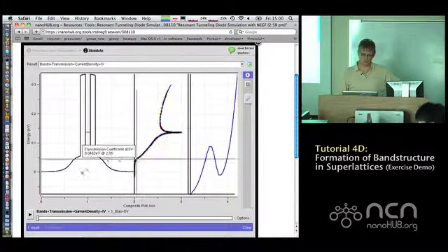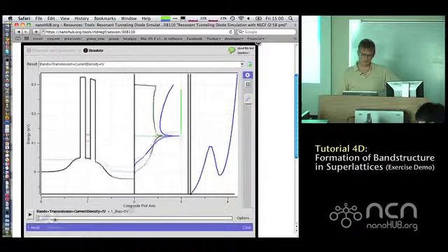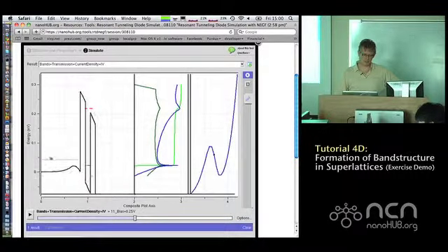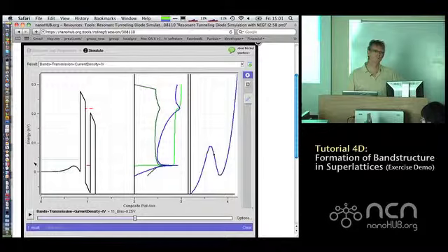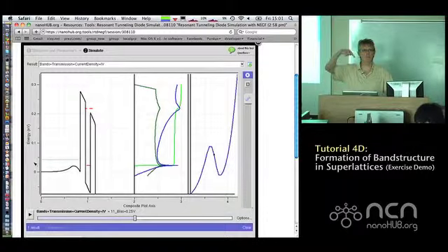Going back to this one question here. So look at this, here is a heavily doped semiconductor. It's degenerately doped. The Fermi level is at 41 millielectron volts above the conduction band. This is like a quasi-metal, right? There's tons and tons of states, and they're all occupied with electrons, right? So that's what we call contact. But further out on the left, there will still be the metal contact. Okay? So I'm not quite sure what you mean by air. I mean, if you think of an STM tip coming down, or? I think I just misunderstood the dot.